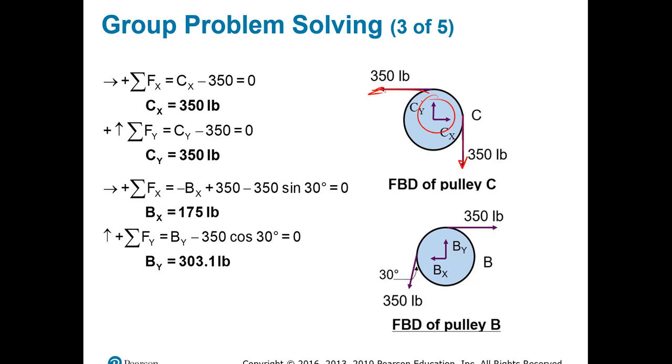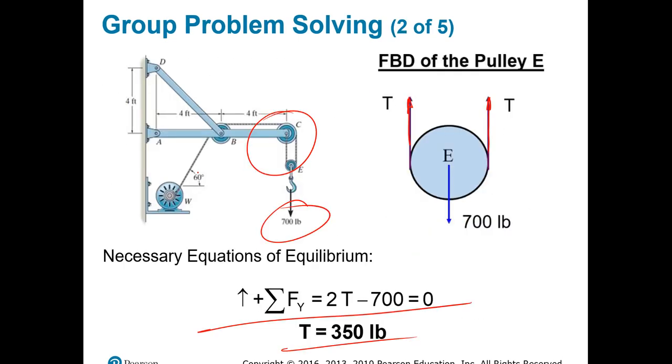So if you simply do a sum of forces in the X and the Y direction, you will get those reactions, CX and CY. Will you need them? Yes, of course. Why is that? Because if you go back to this problem, you will realize that you need all the reactions acting on these pins, and those are the reactions that you need to calculate.